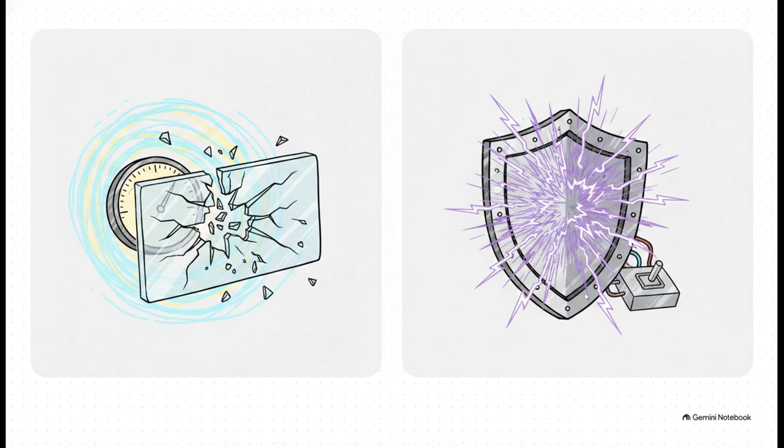On the exact opposite side of the ring, you have protection cores, like class 5P10. These act as a rugged shield. They have to survive and stay perfectly accurate during those massive surges in order to trigger the safety relays.